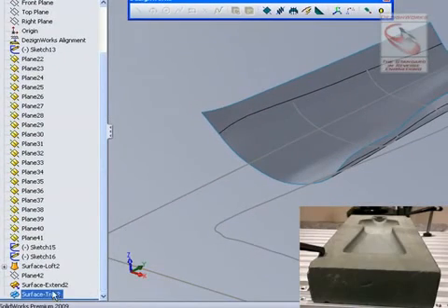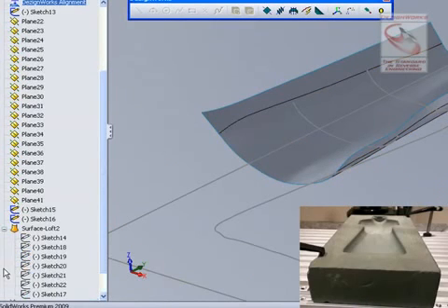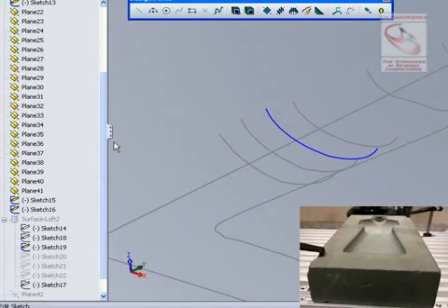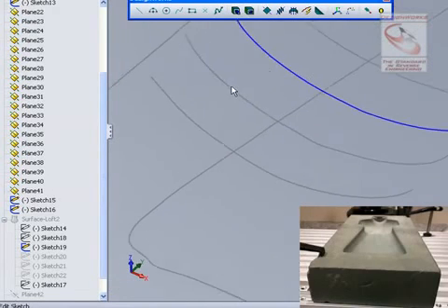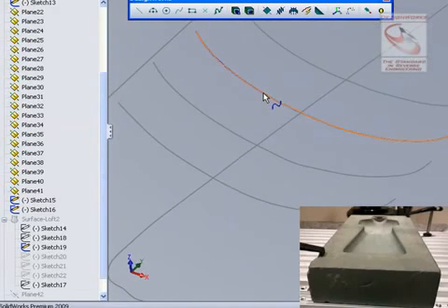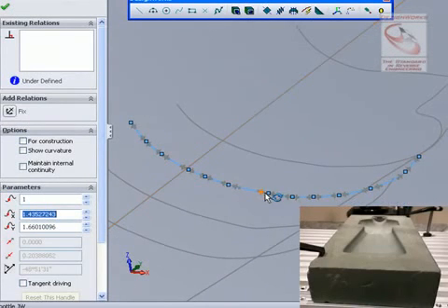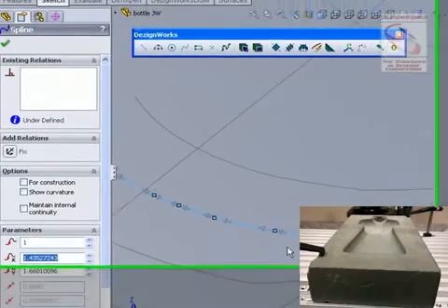So let's say you needed to maybe modify this surface. Notice in the surface all the sketches are there. So possibly there was maybe a flaw in the part. We can actually edit that cross section, interact with it right in Solidworks. Zoom in, select the curve. You'll notice all the node points. So let's say, for example, we want to actually make an engineering change.